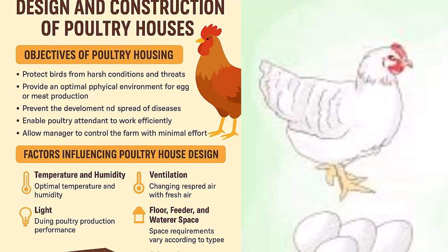The house is too wide, with poor ventilation and wrong orientation; it should be east-west. Insufficient air movement and temperature control. Solution: reduce width, add fans and or ventilation, and reorient new houses.